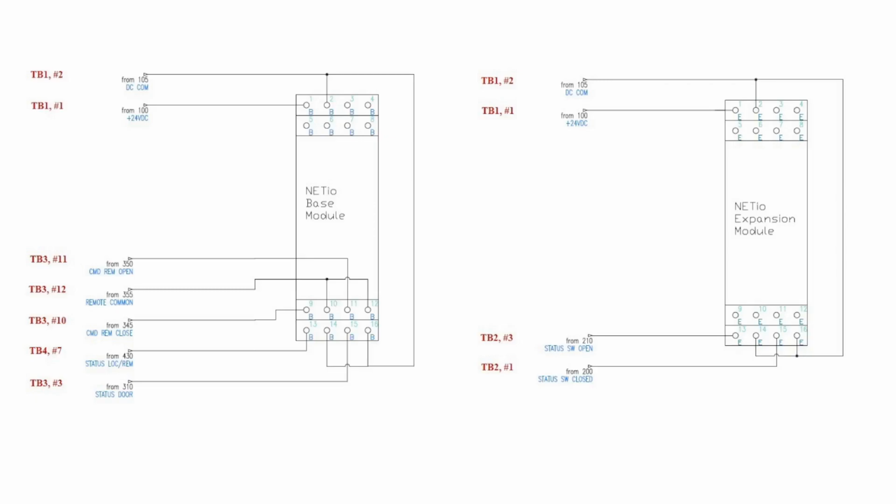For my SECO cabinets, the items of interest are the connections between the SECO main distribution board and aftermarket installed GE MDS radios called NetIO modules, which relay system information and commands over a 900 MHz radio signal. The terminal board drawings take up a lot of room and the wiring can be explained without them, so I'm only showing the wiring going to the NetIO modules.